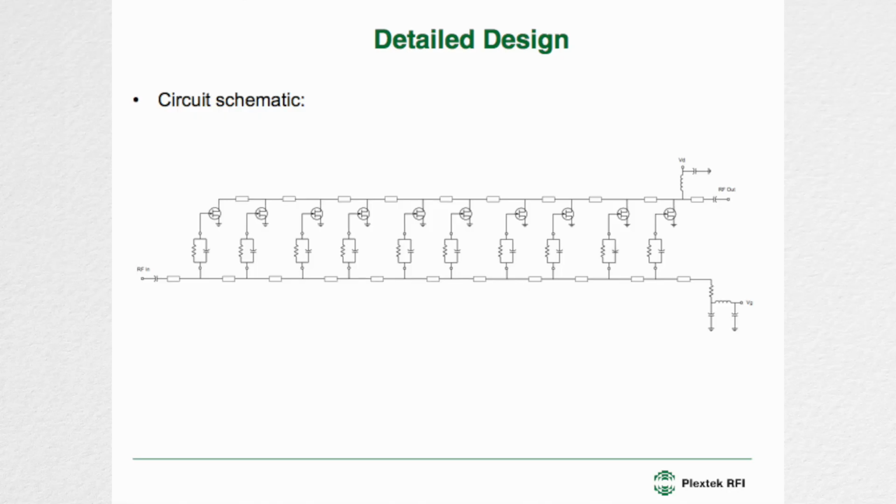And this input is a low-pass filter. These are the series elements, the series inductors, with a termination load here. And these transistors are the shunt elements. So as you make these transistors bigger, the shunt capacitance gets larger and the cutoff frequency gets lower. By adding a series capacitance here, the effective input capacitance is reduced. So you can use a bigger transistor for the same cutoff frequency, but you throw away a bit of gain. Of course, we need these resistances here to get some gate bias in.